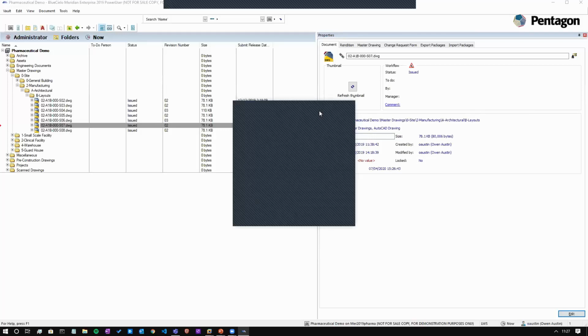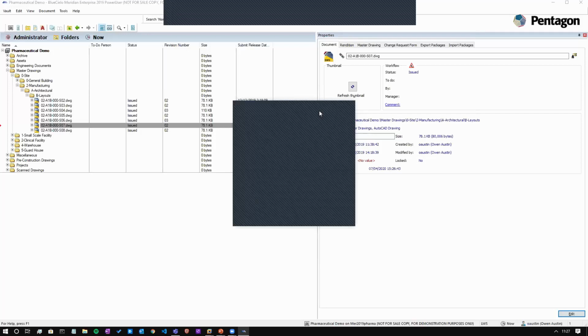So we're opening drawings through Meridian as opposed to opening drawings from our server. Yes, you can open drawings, but from inside the AutoCAD application there's also an integration. Normally you would browse in the application, file open, to a server location. There's actually an interface in there that allows you to go directly into the Meridian Vault. And when you're opening that document, you can also see which X references are associated with that master drawing before you open it.